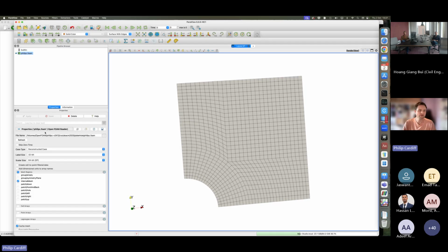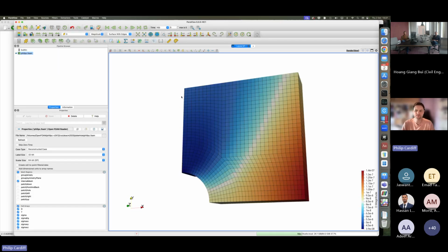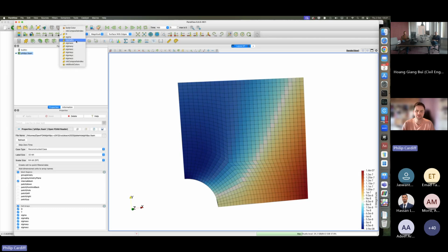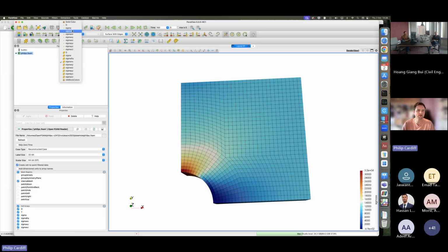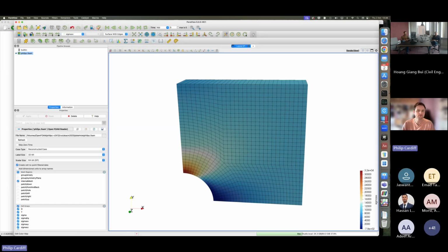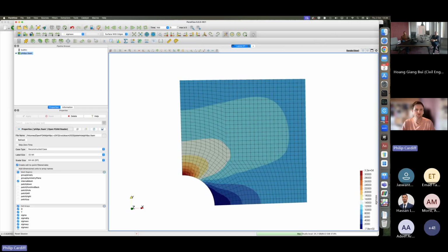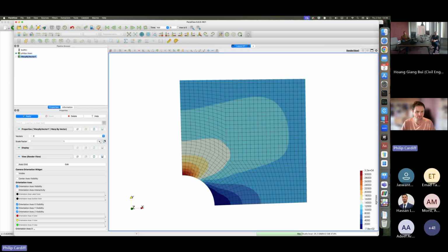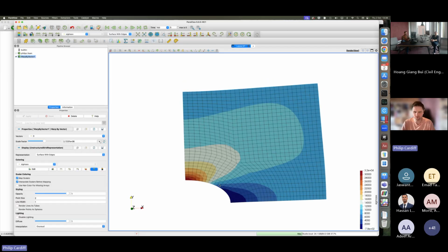So if I open this case and jump to the end time, this is the displacement field. These are the stress fields. This is the von Mises stress. This is the XX stress. I'll just turn on the point data to create the interpolated fields as well. So I will also change this to be contoured. Very good. So there's our stress concentration. It's being pulled to the right. I can warp this as well. Maybe I'll scale it. Okay, so it's being pulled that way. Very good. It extends, and gets shorter in that direction.